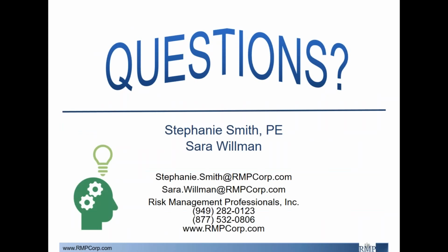So we have two questions from the audience. The first question is, there seems to be a lot of information required for equipment ID. Why is that information so important? Okay, so the question was, why is equipment ID so important and why is it required for each piece of equipment? One of the biggest reasons would probably be because eventually those nameplates will be faded, worn, perhaps damaged, and in the meantime of ordering a nameplate from the manufacturer and getting a certified nameplate for that piece of equipment, it's helpful to have that information in a secondary place.